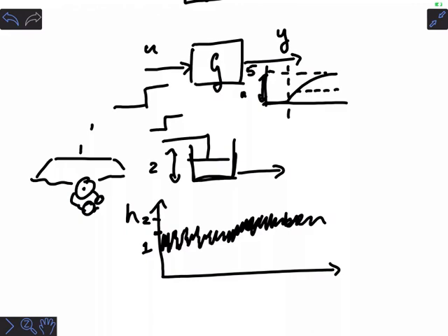Of course, there are people who are paid to watch the screens and make sure that nothing blows up, and those people are very cross at you now because they are paid to keep the plant running at some optimal position, and you have just told them, I'm going to push it away from that optimal position and keep it there for a while. We're going to be making off-spec product for all of that time. And why? Well, you know, I just want to get a feeling for how it works. Not popular. Okay, so this is what I mean by old school step testing.